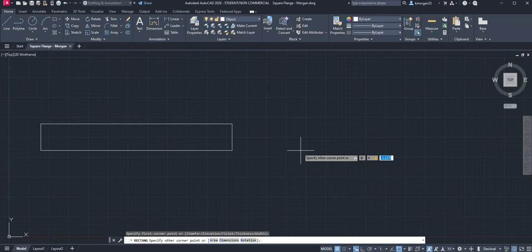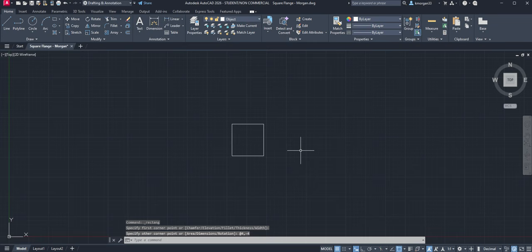Don't worry about whatever is going on in the drawing area, that's just the computer. Now we are going to specify the next coordinate. So we enter a number, comma, -4, with the relative coordinate input coding. Then we just press enter on your keyboard and you are going to get this.